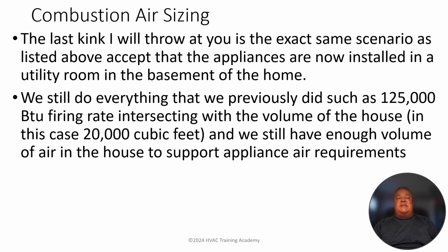So we're going to have the exact same scenario as the one listed above, except that the appliances are now installed in a utility room in the basement of the home. So we still do everything the same way. We got to find out, does our building have enough air, which it did. So we're good to go there. But now, because of the case, we've got to check and see how much air is there inside the room where the appliances are going to be located.